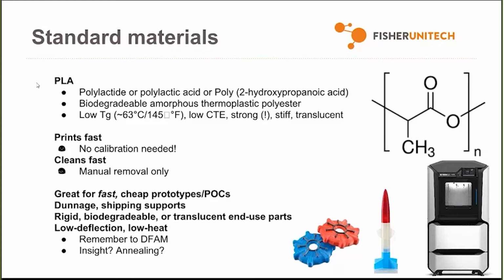Anyway, in practice, PLA is really easy to use if you understand its limitations, one of which is the lack of a great support material. Because of those magic combinations of properties, it's hard to find another material that's close enough to use as a support material. And that's why most PLA printers on the market have a single nozzle, and so they build support structures out of PLA.